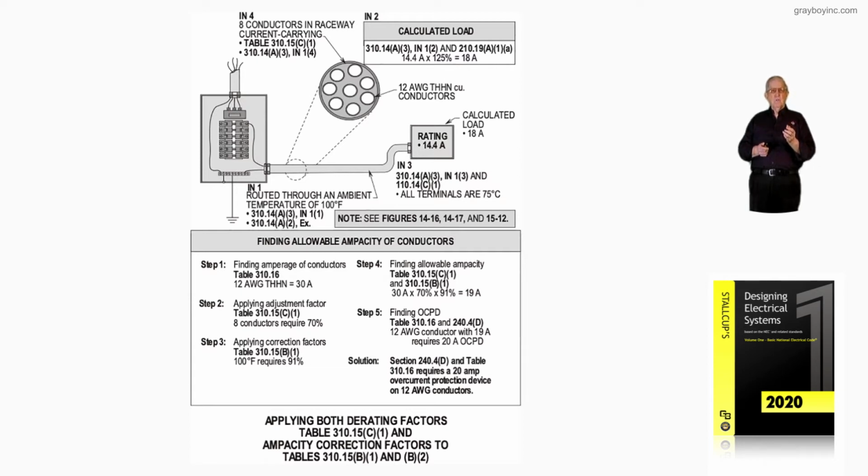So step 2, 47 amps, 50 amp overcurrent device, number 8 wire from the THHN column can be connected to that 50 amps. So a 50 amp overcurrent device using number 8 THHN copper conductors are required.